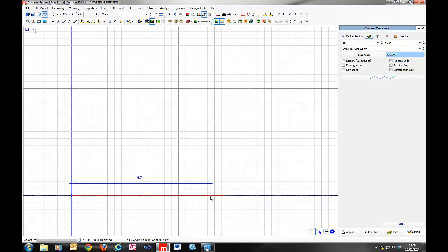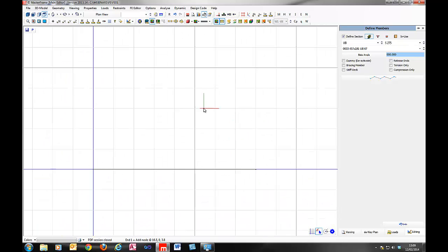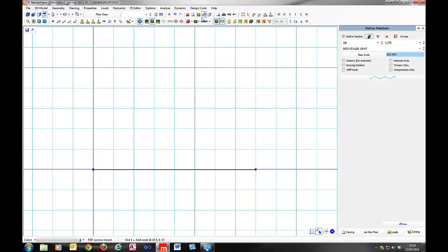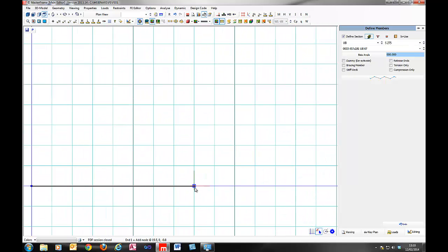So we're going to use those today, and I'm simply just going to start snapping and drawing, and what I'm going to do is create a wall or a side of the structure which is 20 meters long. So I can actually just start typing 20 here, and that will override the current dimension and direction. And I'm just going to turn on my DirectX graphics, and my line produces itself a little thicker there.